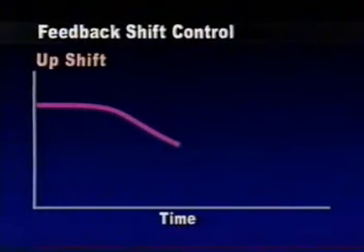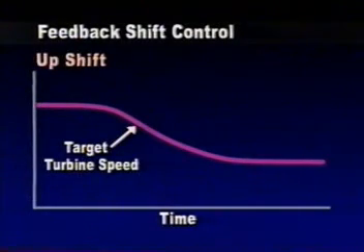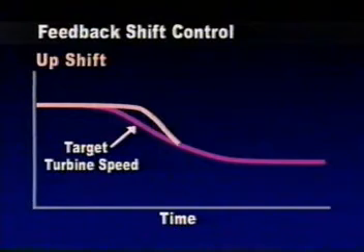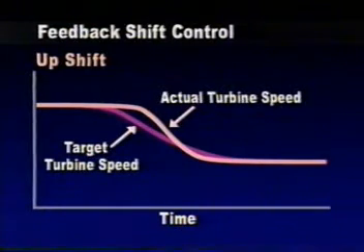Feedback shift control feeds back solenoid valve duty ratio so that the speed change of input shaft approaches the predetermined target change ratio in shift to each gear. So, it is possible to control ideally the sudden fluctuation of torques in transfer.